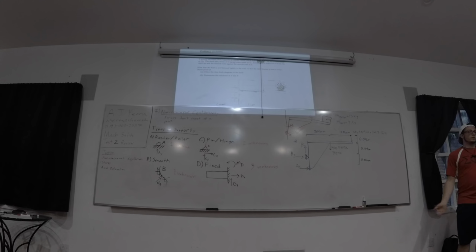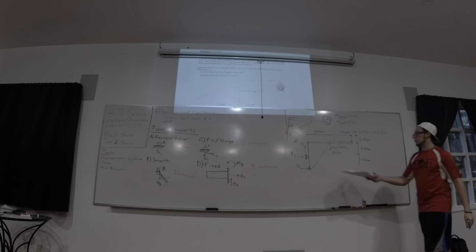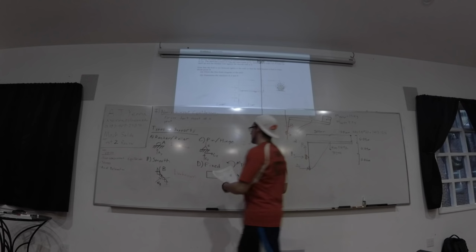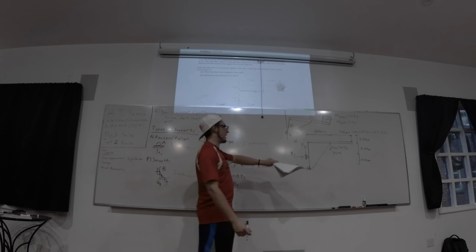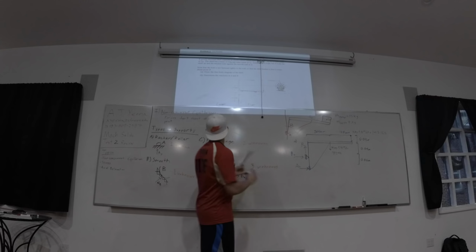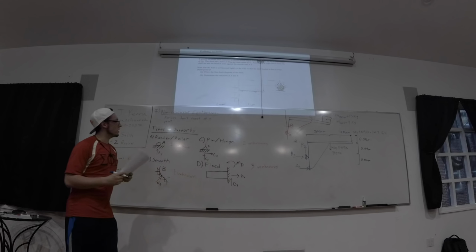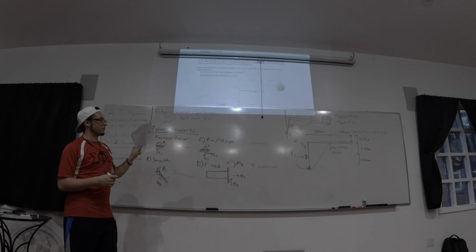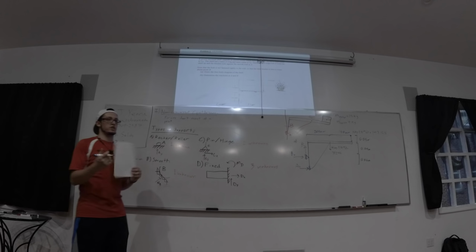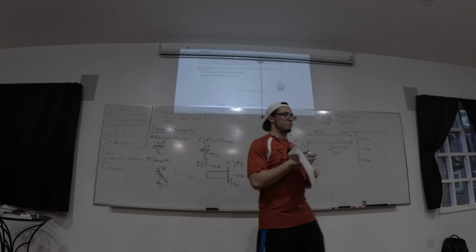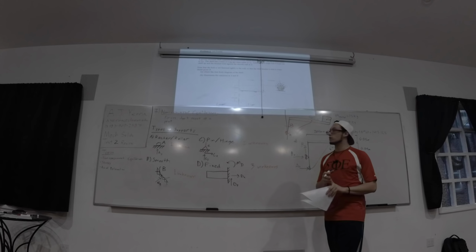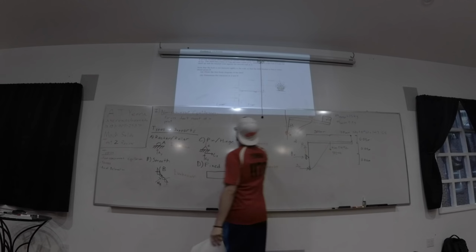Part B was to determine the reactions at A and B. So solve for these three forces. This is bringing you back to test 1, where you have a force moment system and you get 3 equations, because for non-concurrent equilibrium, instead of just sum of Fx equals 0 and sum of Fy equals 0, you also get the summation of moments at any point is equal to 0, which are your 3 governing equations.